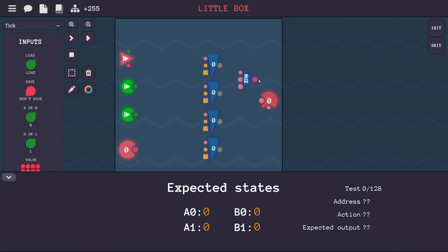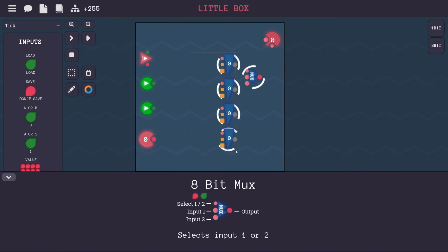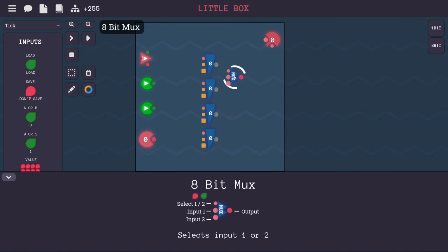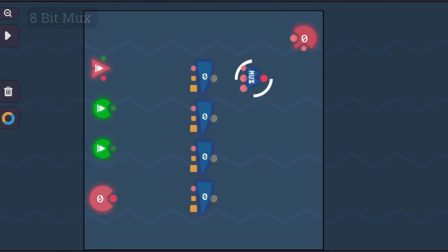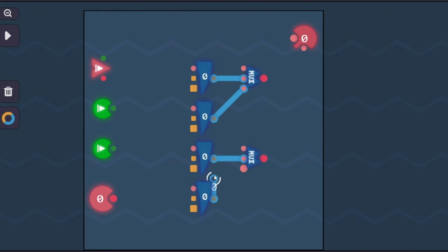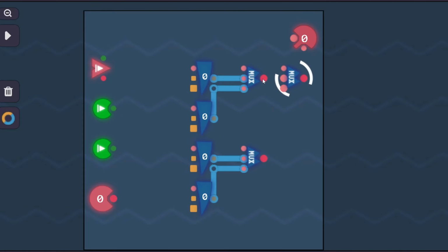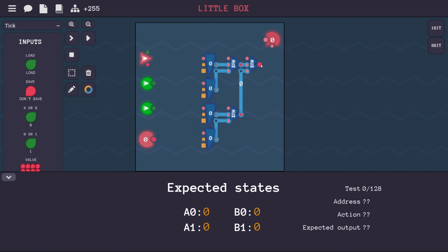And let's start by thinking about selecting our outputs. So we could select between our outputs here by connecting this first one up. So here's going to be our A multiplexer out, and let's have our B multiplexer here. And then we'll need one more multiplexer to choose between A and B. And if we just need to connect up the signals here.